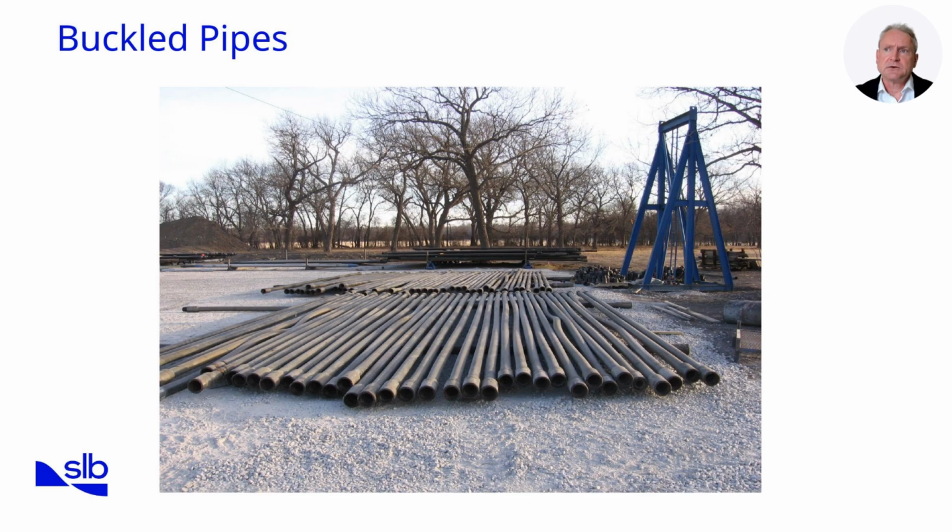This slide shows a photograph of drill pipe that has buckled inside the well bore. Notice how the pipe has deformed into a series of bends rather than maintaining a straight profile. This deformation is the direct result of compressive forces exceeding the pipe's stability limit. Once buckling occurs, the pipe pushes repeatedly against the borehole wall, creating high side loads, friction, and wear. In severe cases, the pipe can lock into a helical shape, making it very difficult to move or rotate. This image demonstrates why buckling is a serious operational concern that must be addressed in design.